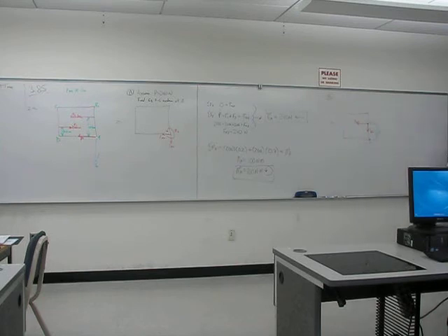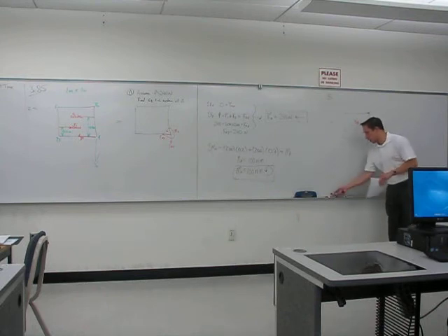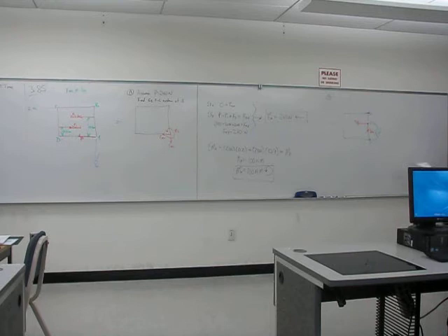Okay, because it asks us to find two things. It asks us to find the force that we should apply to some point on the edge called AB. B is the top corner up here. So I chose my point on that edge as the point E, and I'm going to apply some force that might have an X and a Z component, and I'm going to say that point E is located D meters away from point A on the edge. If I wanted to take the measurement from B, I could. It worked just as well.